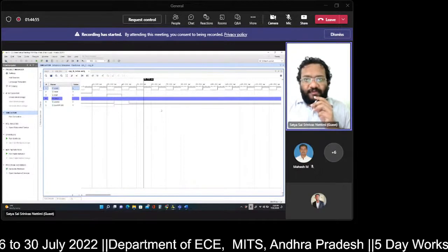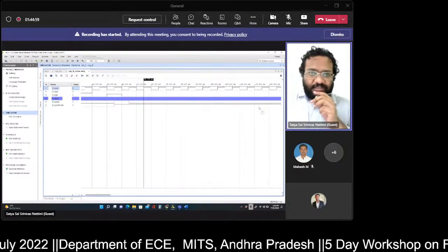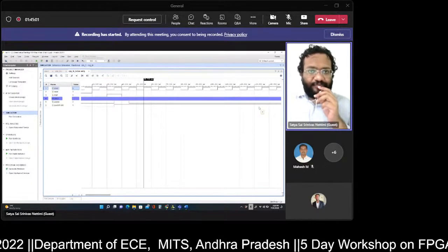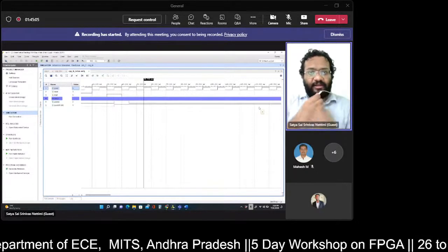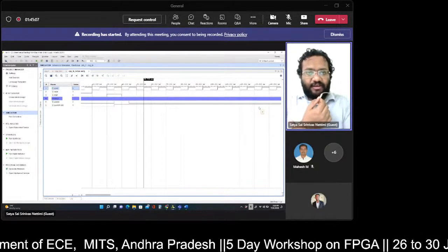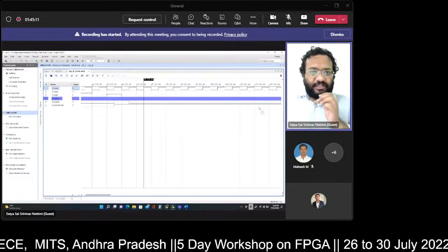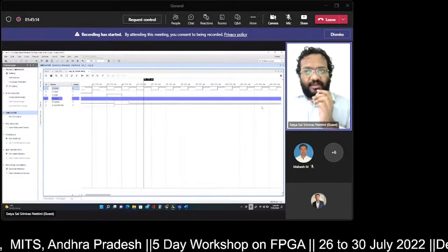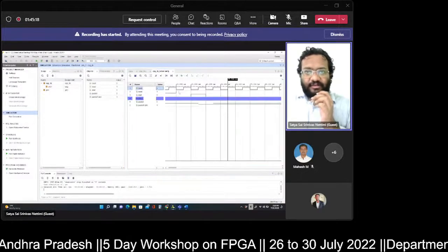Now after 55 nanoseconds, the output is constantly 0. That is the invalid data. So from here, for 2 clock cycles, the frame packet data is valid. So I think we have successfully generated 2 bits in the packet. Now we will see how to proceed with the further generation.